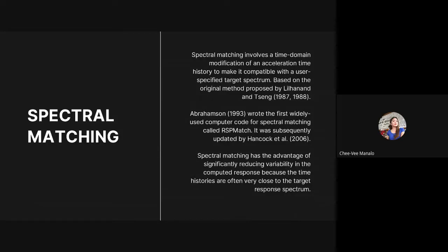There are other methods to match the design spectrum. And let's talk about the second method, the spectral matching. It involves time domain engineering so that the response spectrum is compatible with a smooth target spectrum. It can be a polyline design spectrum or a hazard spectrum.